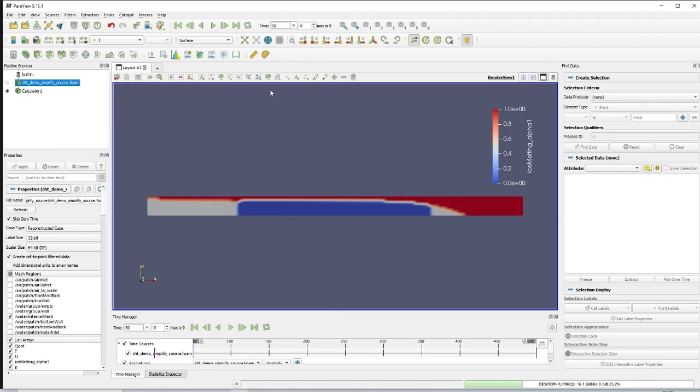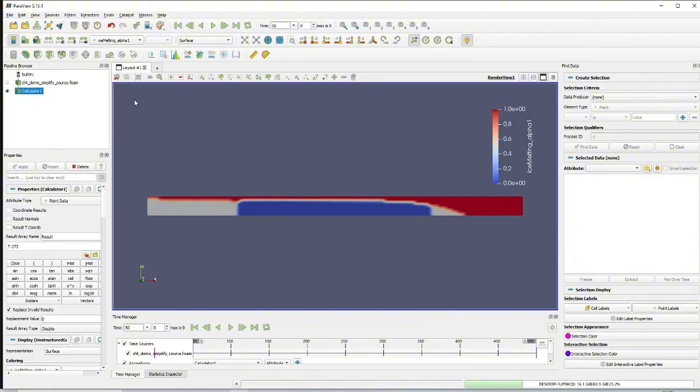Also, after 1 minute, there's some heat brought in from the right side and from the top side, so it started to melt. But it will also introduce some overcooling of the water and may cause some formation of ice as well. So not a fully ice zone, but some ice. And then when I go forward, more heat will be transferred into the ice region, and gradually the ice melts until completely melted, right?